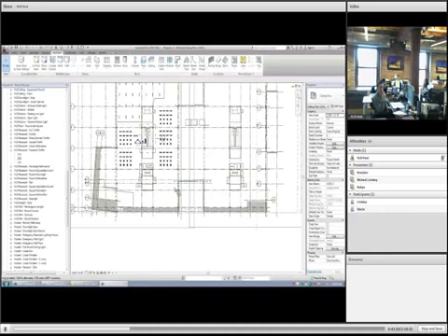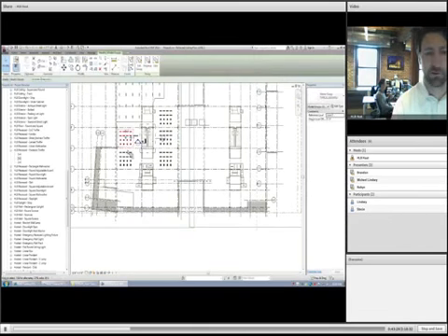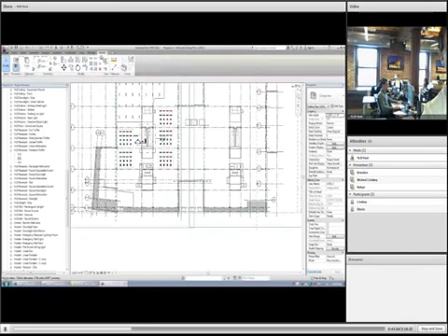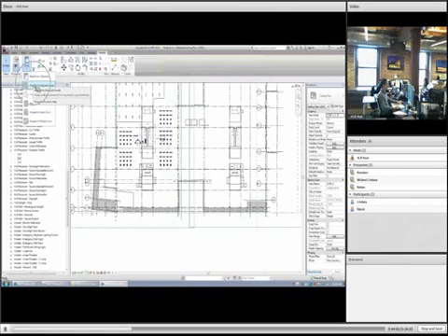Okay, what if we have the same thing going on the floor above? That's common, right? Let's select all of those groups that were created. I'm going to do a Control-C. And I've used my non-hosted fixture, and that's one thing. For this to work for everyone, that's going to be the demand, because we don't have any work planes up above for them to host to. But we do a Control-C. We go to our Modify tab, Paste, Aligned to Selected Levels.